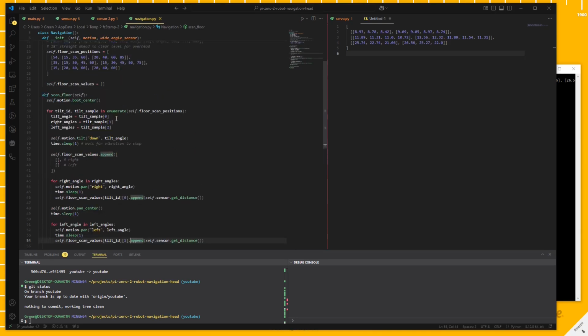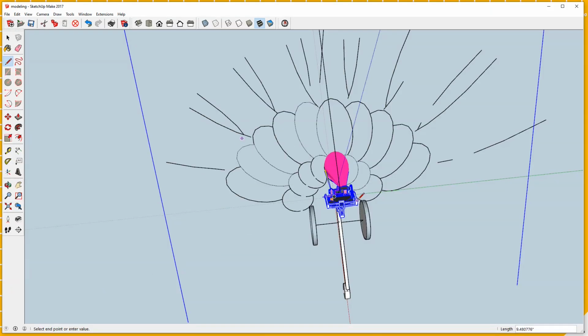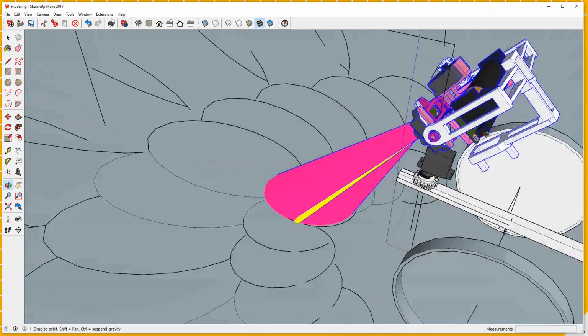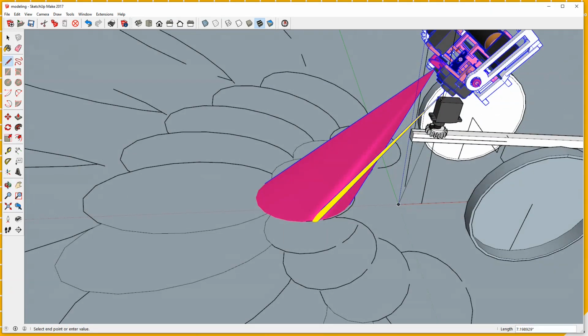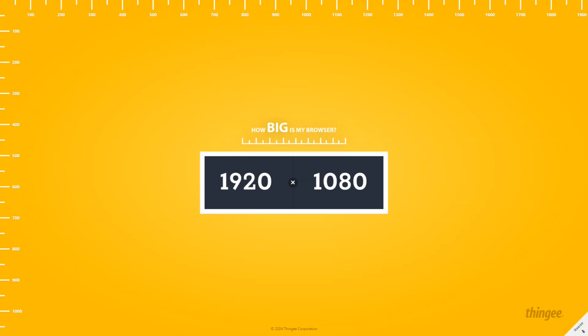But anyway, you call scan center or scan floor, and it'll center all the servos so the beam center line is parallel with the ground. We're talking about the center of the IMU, which is the rotation point. I should pull this up, sorry. When you center, that's like exactly upright, exactly horizontal. I don't want to say exactly, it's pretty...